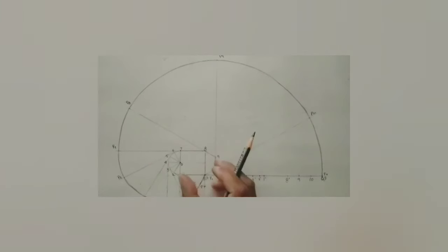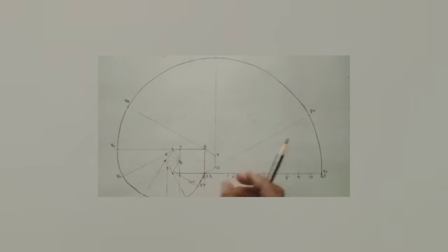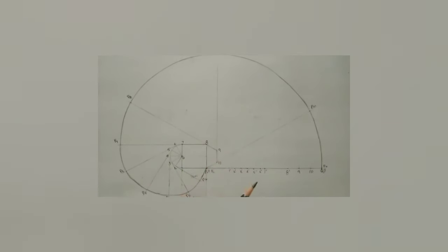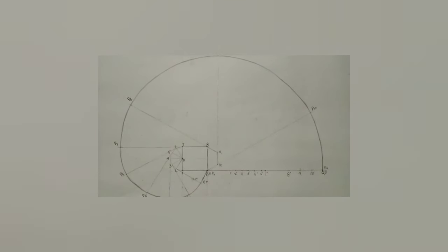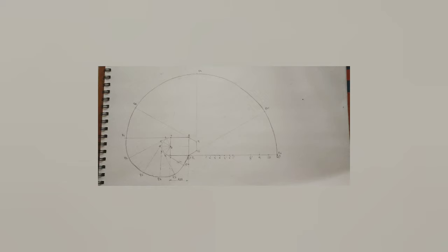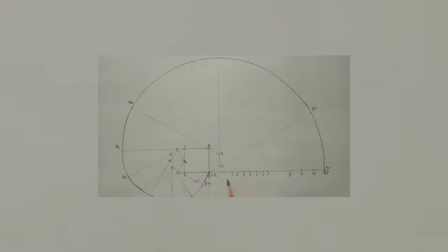Okay, and after getting the involute, mark the given dimension. What is the dimension given? Square length has been given. Each side of the square length, how much is it? 30 mm. Outside the diagram, extend the lines here as the dimension line at the center. Just take one small square and mark 30. The meaning is each side of the square is 30 mm. No need to mark all four sides. Okay, this is the method of drawing an involute for the given disk.